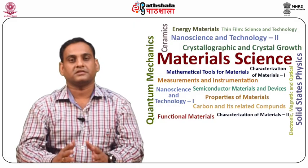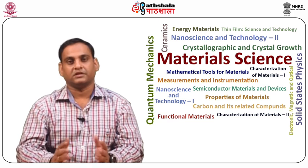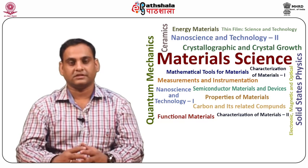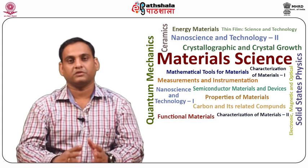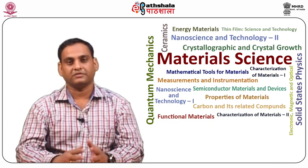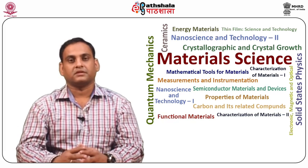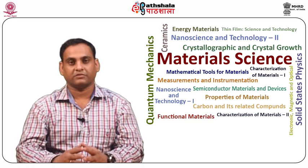A special class of amorphous metallic alloys, particularly known as bulk metallic glasses, can be synthesized from the melt with very low cooling rates. BMG are not discussed further since this is focused on soft magnetic materials, which can be obtained only by rapid solidification or mechanical alloying techniques. There are 4 technologically important classes of magnetic amorphous alloys.